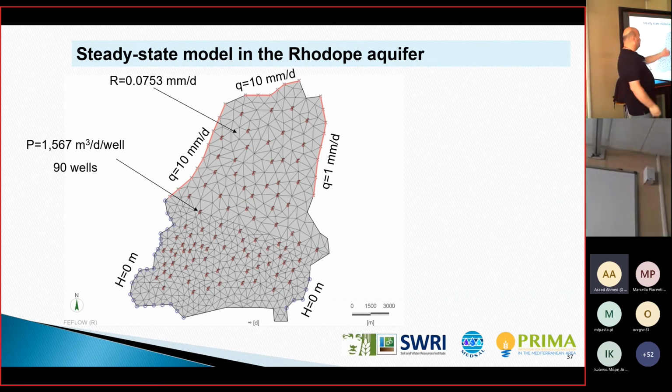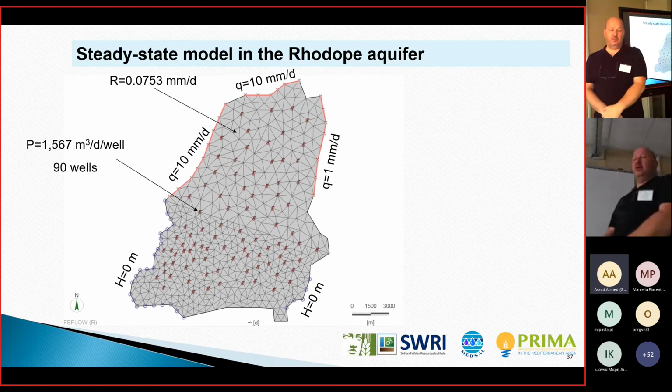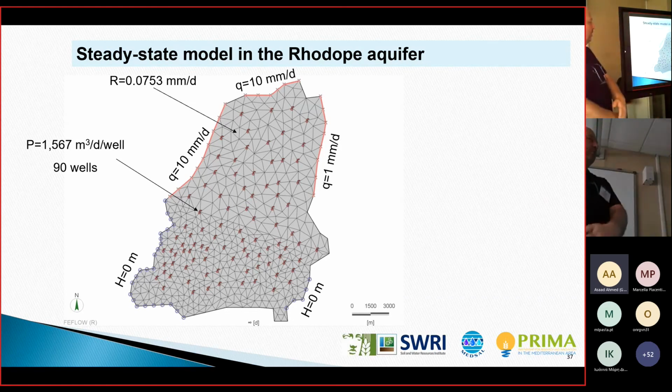Okay. So, starting from the beginning, this is a second type boundary condition, right? Because you have a lateral flow. You remember? So this is the second type boundary condition. This is the first type boundary condition. This is not a boundary condition, or the fourth type that we said before. Okay. And the recharge is on the top of the unconfined layer. We can say that this is more or less a second type of boundary condition.